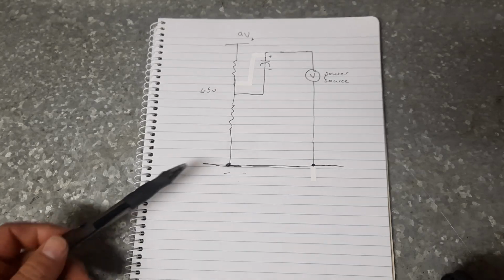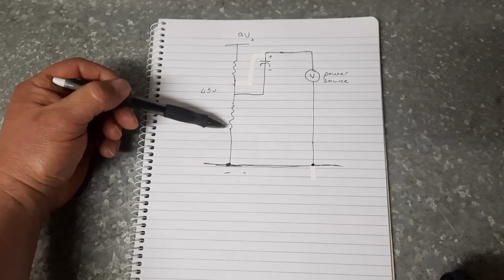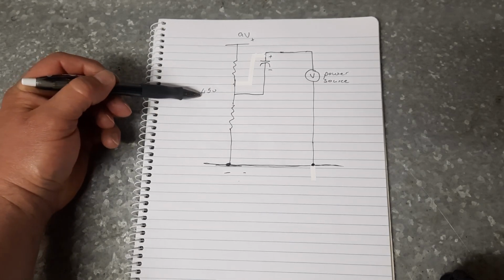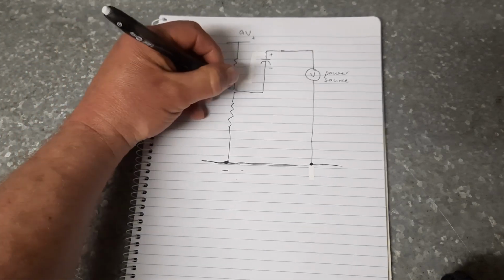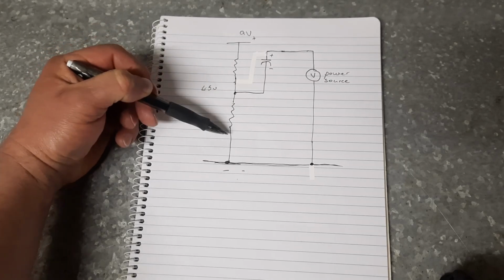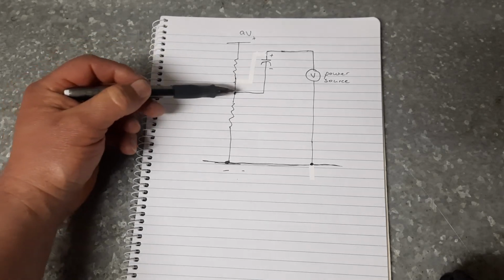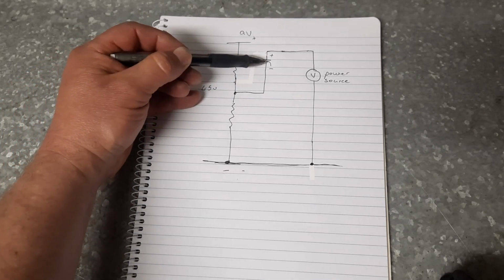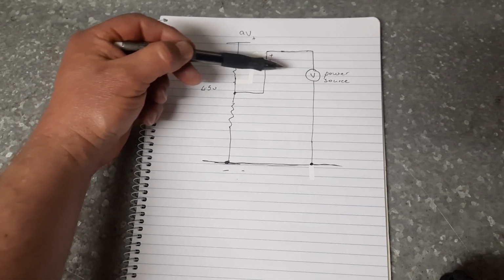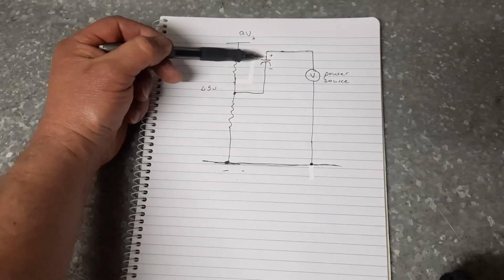Looking at this now, this is drawn a little bit different. Let's say we still had our voltage divider here that was still dividing it exactly in half, so we're getting 4.5 volts at this point here. So we've still got 9 volts across it. We've got a 4.5 volt drop here, another 4.5 volt drop here, exactly 4.5 volts each resistor. The negative plate of this capacitor is still at 4.5 volts. So for us to charge this, the power source has to be above 4.5 volts.